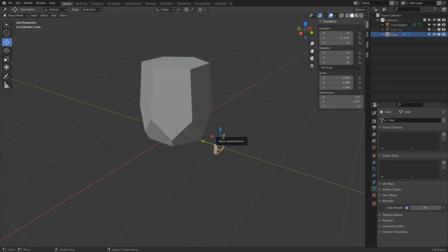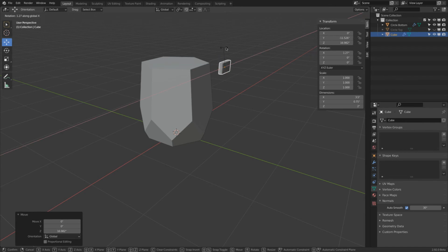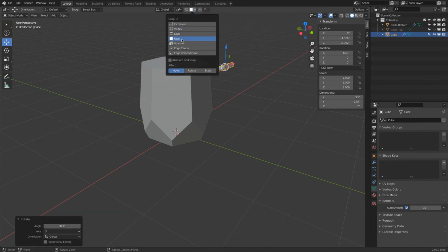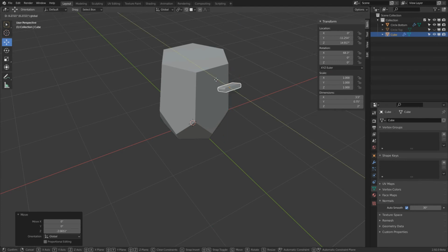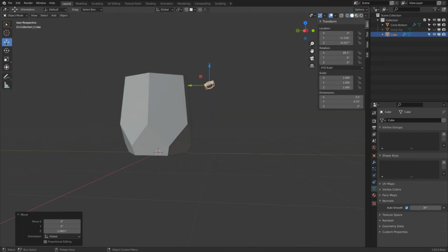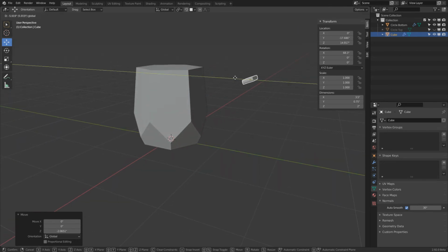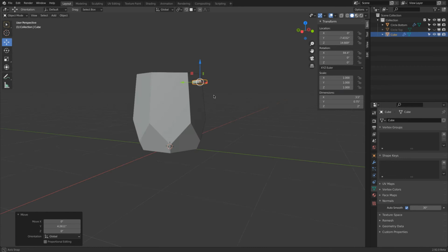Okay, so how do we get this now to here and perfectly rotate it? Check this out. Bring this one up. R and X, rotate this a little bit. Snap to the face and align rotation to target. So I'm still in move mode, and I move this to it, and I want it to snap onto the face. Hold Control, and there it instantly rotates it.